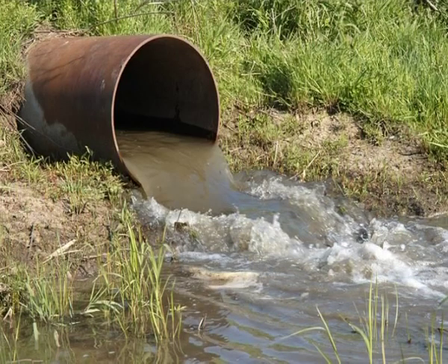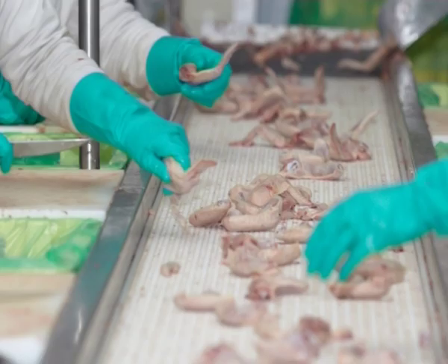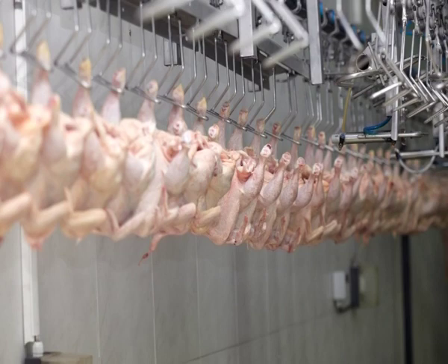Wastewater pollution levels depend on the kind of raw material being processed, on the plant technology, and the amount of wastewater generated is also an important factor, as the concentration of pollutants is inversely proportional to it. The general characteristics of the wastewater generated from different food industries are as follows. For example, in the meat and poultry industry, the wastewater generated from slaughterhouses and poultry processing will have a high organic load, which may go up to 8,000 milligram per liter BOD. It also has a high concentration of oils and grease, salt, nitrogen and phosphorus, with suspended solids at 800 milligram per liter or more.